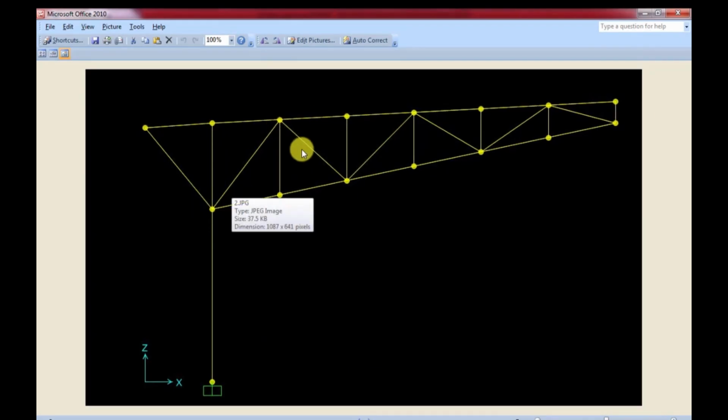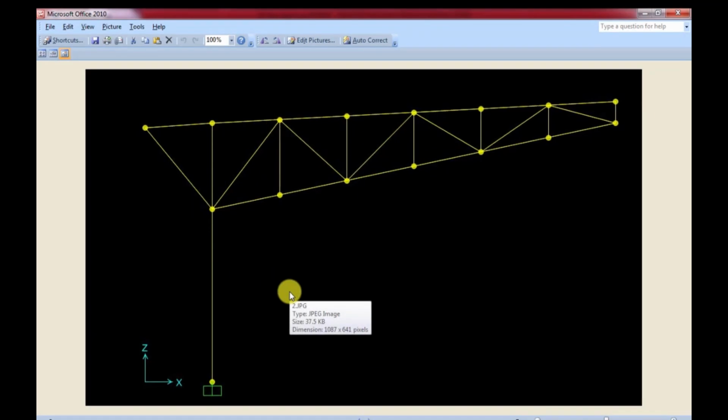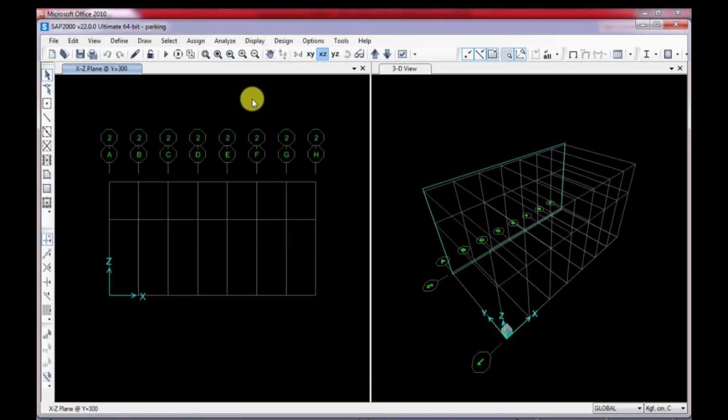Next, again click on Import New Property, and this time select Tube Sections. Choose 100-100 box and 80 times 40 box. You can hold Ctrl to select multiple sections at once. Click OK to import all selected sections into the model. Finally, quickly verify that all sections are assigned to ST37 steel. Now, let's start building the truss model geometry.